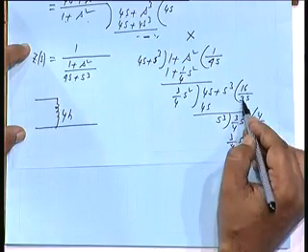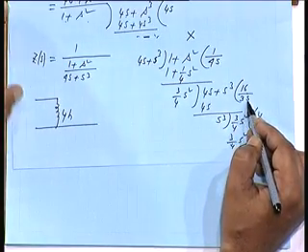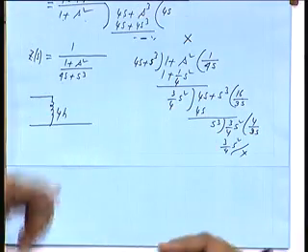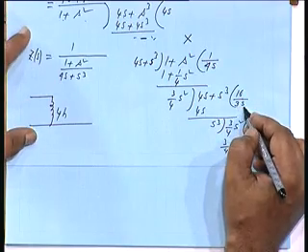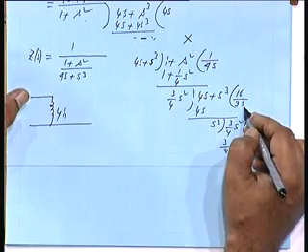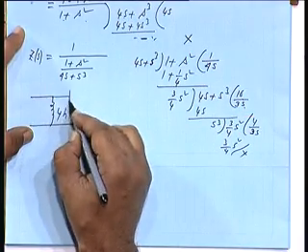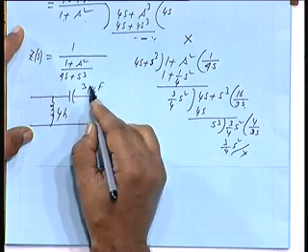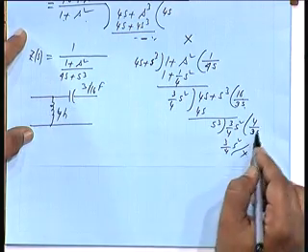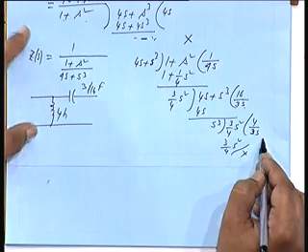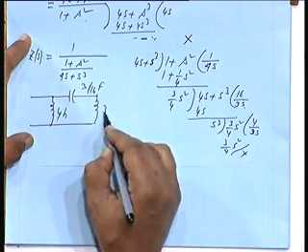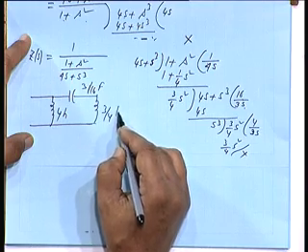Then 16 by 3S is the impedance. Alternately, it will be impedance, admittance, is it not? So, 16 by 3S is the impedance. What is this? 3 by 16 farads. Okay. And then 4 by 3S is the admittance. So, 3 by 4 Henry inductor.